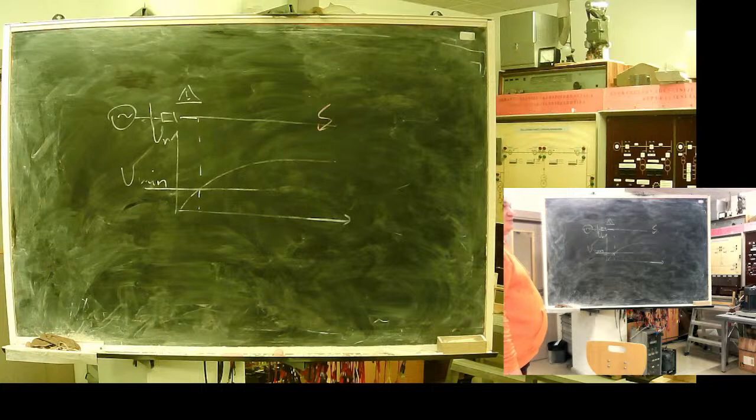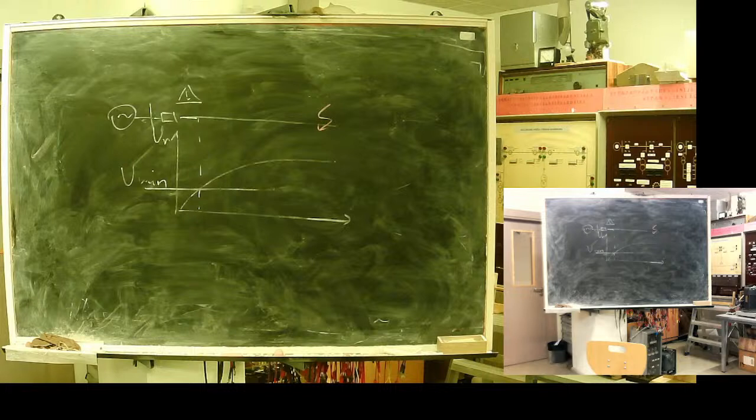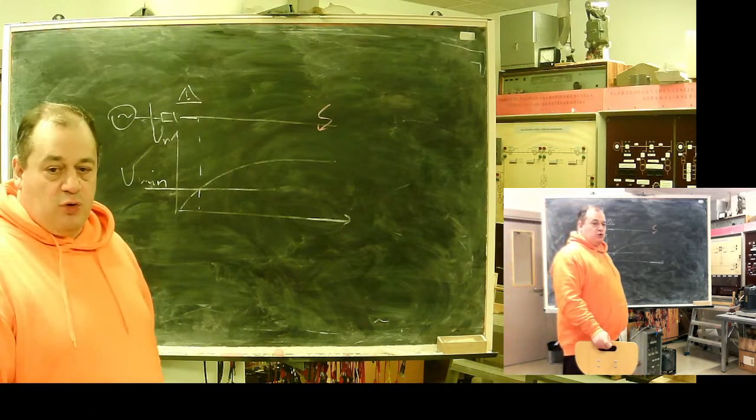The first thing done with relays is a function of memory. Relays do remember, even old analog relays remember at least the direction of voltage before fault. Old relays had a resonance circuit powered from the third phase voltage.